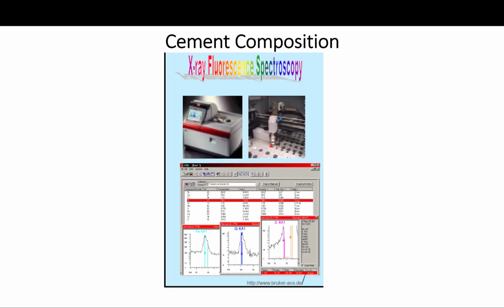So back to the oxide analysis. I'm going very fast with these slides. Back to the oxide analysis, which is more commonly used, mostly on the cement mill certificates. That's what you get. This is referenced by ASTM C114, and a common methodology also used for oxide analysis is X-ray fluorescence spectrometry, abbreviated as XRF. The instrument is shown here.